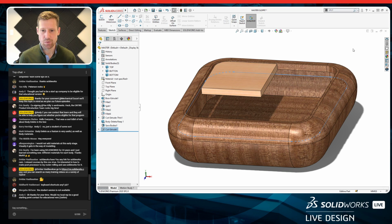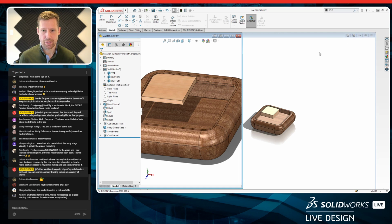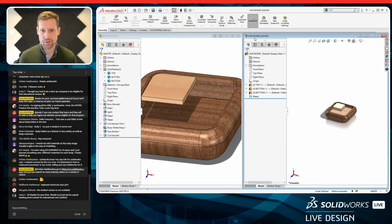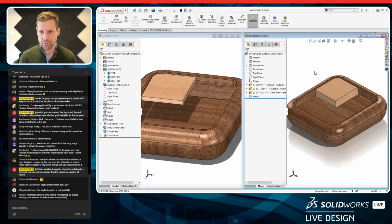Okay, so let's talk about what's happening here. I have a cut extrude. It's underneath my save bodies feature in my feature tree. So I'm going to pan this over here to the right, and let's take a look at the save bodies assembly that was created with those parts. Notice that nothing has happened to this yet, although it does contain all these parts in here.